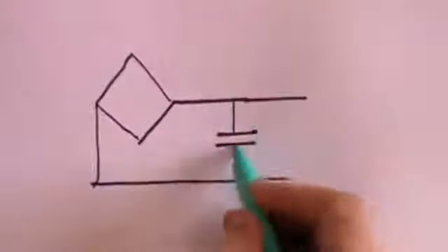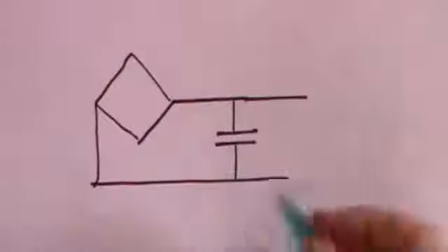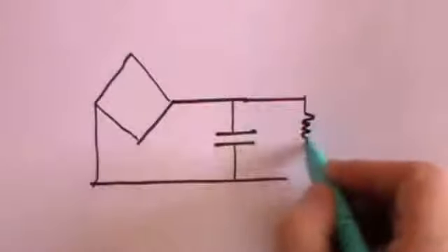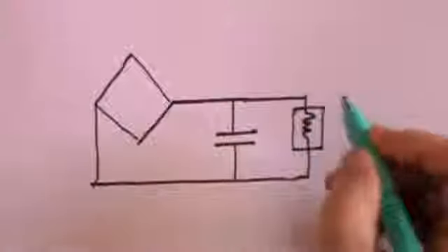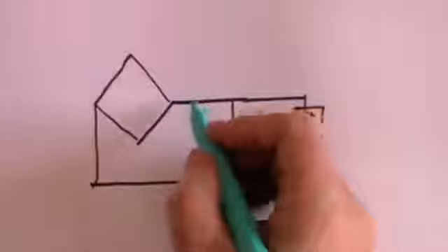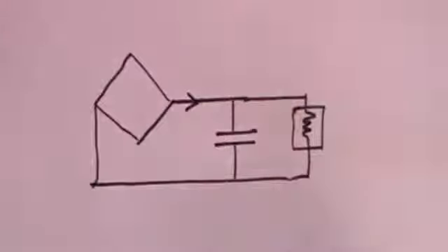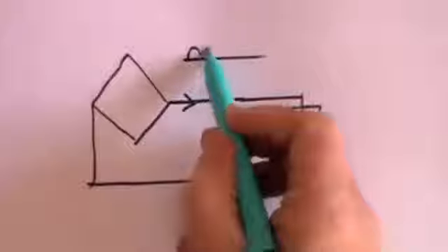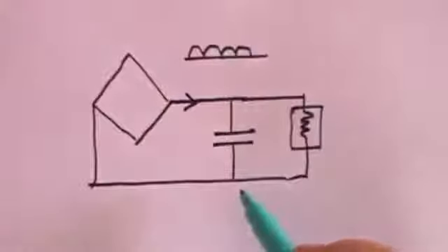Well, what we do is we take the output of our bridge rectifier. I won't bother drawing in the diodes. It's exactly the same diagram as before, but here is the output. And what you will need to do is to put a capacitor, a large capacitor, in here, and now this can be your computer, which is your appliance. What happens? We know that the current is only going to flow in this direction, but it's going to be a constantly changing current and voltage.